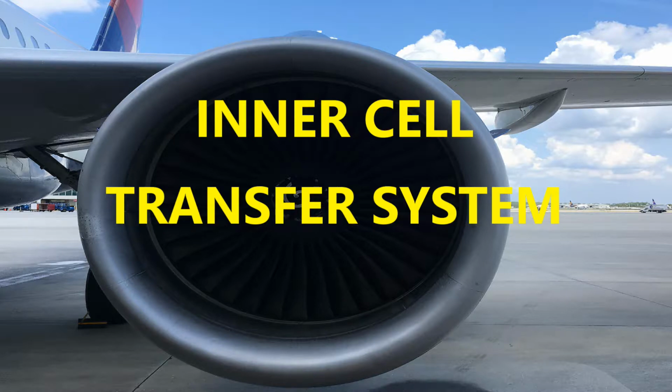So let's look at the main pumps here and talk a little bit about the pumps that go along with each of the tanks. The pumps are your 3-phase typical 115 volt AC motors, and they're actually installed in a canister. So if you see the word canister in the AMM, that's why, because they're encased, installed in a canister. The pressure is going to be limited by sequence valves. It's going to allow center pump priority first. Sequence means in a certain sequence, a certain priority order.